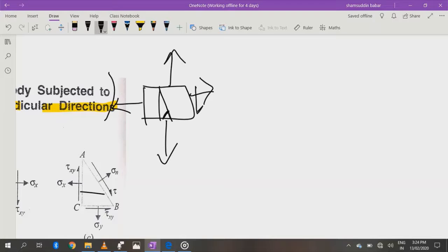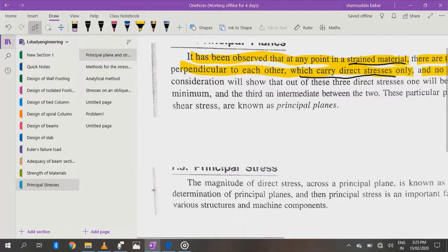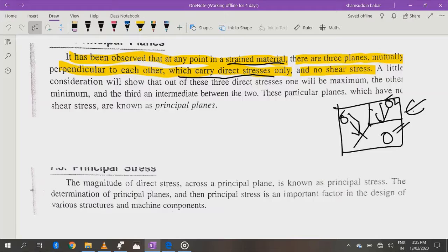Now we are giving this as stress x and this stress name as stress y, and the shear stress as txy. Okay, now you need to understand major tensile stress, angle from major tensile stress, angle from major principal plane. Now we are also assuming that stress x is greater than stress y.